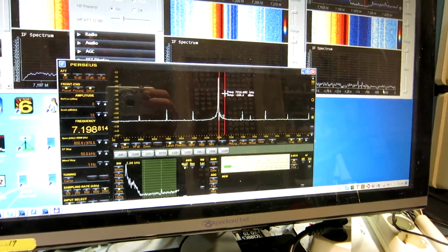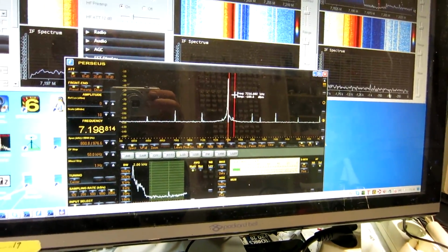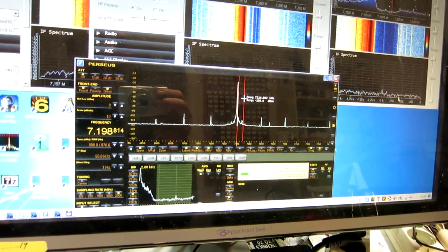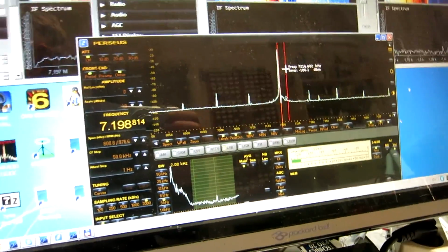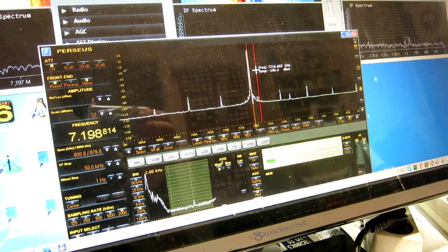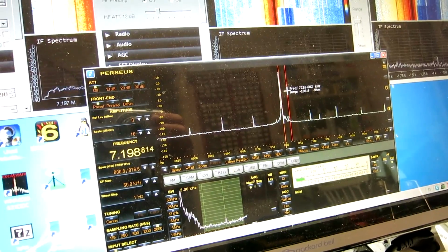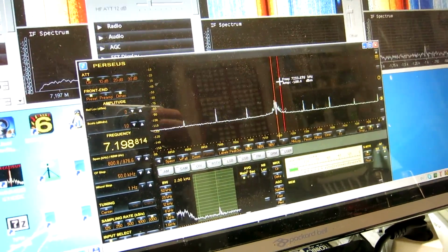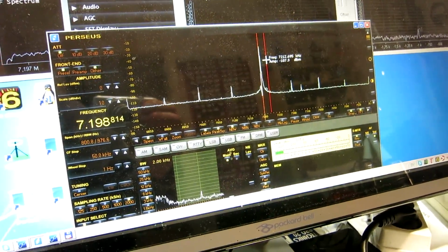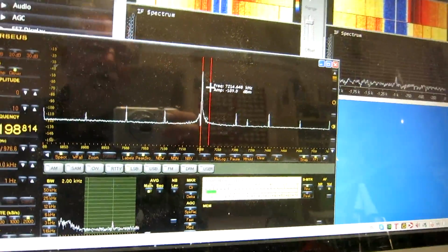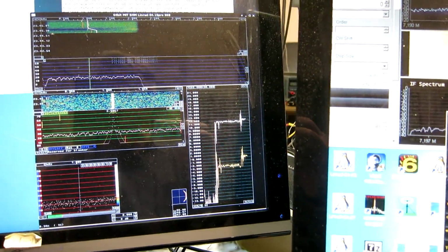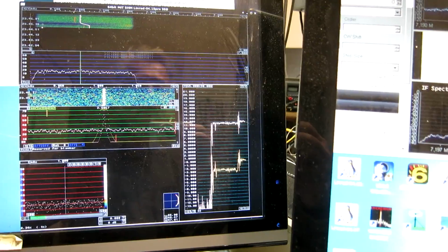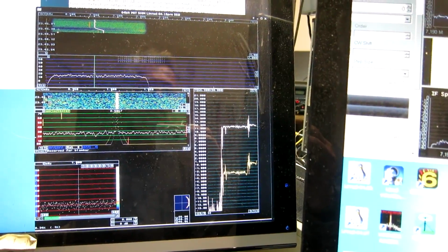Now I move the interference to the other side of the desired frequency. So I step 4 kHz upwards, once and twice. And now I am on the other side, and I have no degradation. I have to increase the level. The notch filter is not quite symmetric.